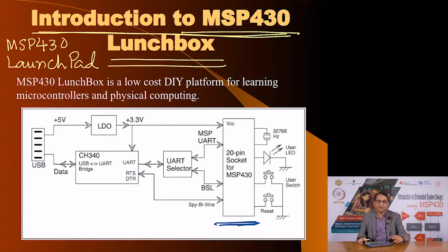All you need is knowledge of which signals to activate and a mechanism to connect the desktop computer and the microcontroller. And today, as you know, one of the most common methods of connecting anything to a desktop or laptop computer is through USB. Unfortunately, the G2553 microcontroller does not have a USB interface. It has a UART interface.